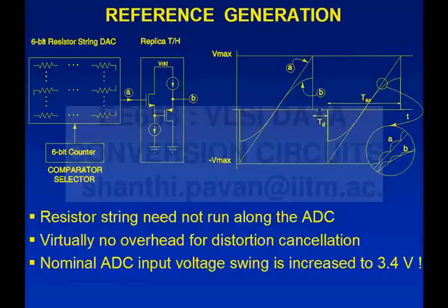So this is the 6-bit resistor string which is used to generate the linear references. Let's say you want to AUTOZERO the 34th comparator, then this will read 34. So the 34th preamp is, in principle, pulled out of the array. So the AUTOZERO switches are closed around there. The code 34 is given to this string of resistors. So you will tap off, using a mux, the output of the 34th resistor.